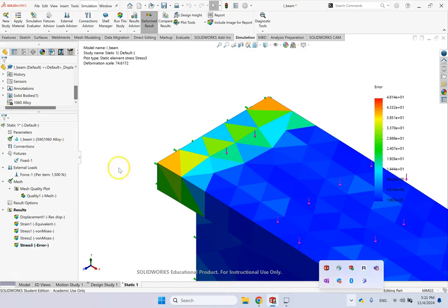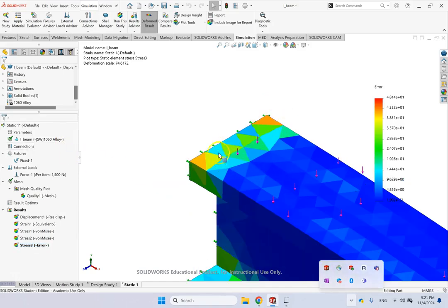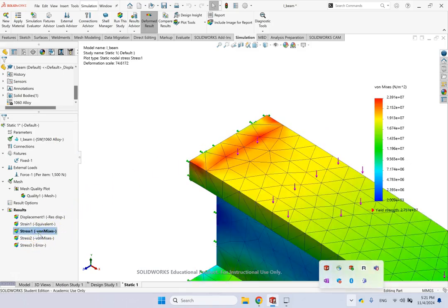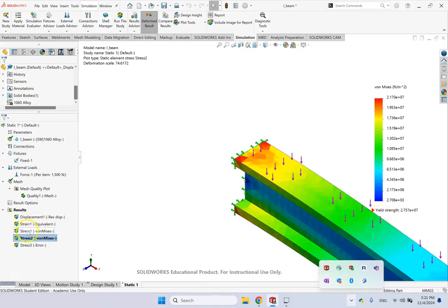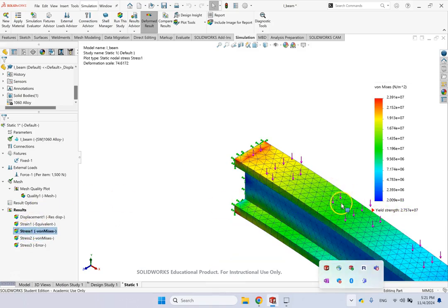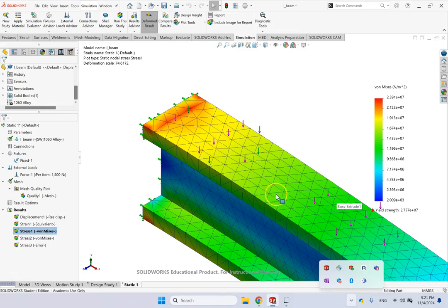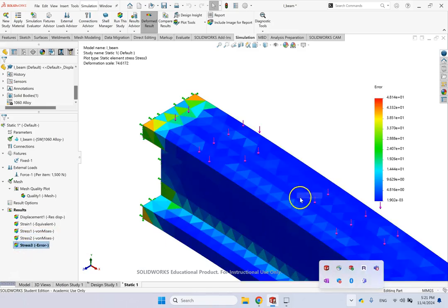And you get that. And if you see the high values in this energy norm error, it is when the difference between the nodal values and the element values is high, right? In these regions, correct? Look, in these uniform regions where all nodes are green and the average of the element is also green, you will see very small errors.